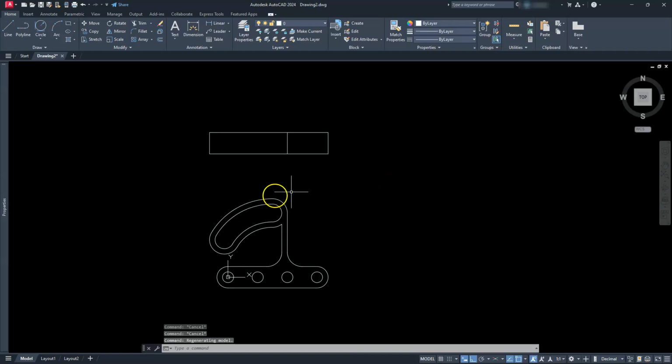Next, we're going to use this in order to create the isometric. So this is where we're going to take a little bit more time at it, and hopefully it won't take us too long, but we'll go nice and slow and make sure we can grasp it. I'm going to first switch my ISO draft on, and then I want to take a look and stay in the ISO left plane.